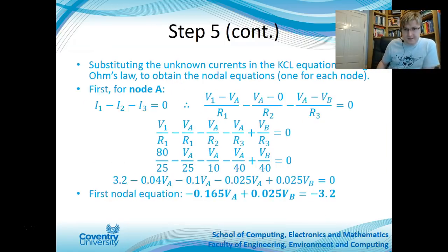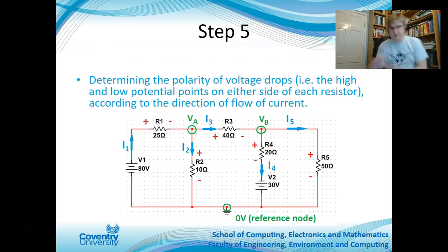If I go back to the main circuit, you've got two current sources, so you could do mesh analysis on this. The only trouble with mesh analysis for this is you would end up with 3 unknowns. So you would have one loop here, and one loop here.